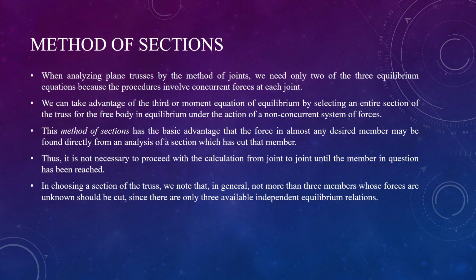This method of sections has the basic advantage that the forces in almost any desired member may be found directly from an analysis of a section. Thus, it is not necessary to proceed with the calculations from joint to joint. You can directly reach the member in question.